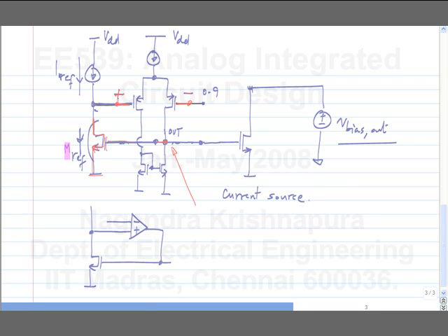So what do we need to do now? No, but if it is oscillating, that's it. The circuit doesn't care whether you think you want it in DC or AC, right? It will start oscillating. What will you do? You look at this output, any point in the circuit in an oscillator, it will have some oscillatory waveforms. Okay? So what do I need to do now? Compensate it. If it's oscillating, I have to compensate it.